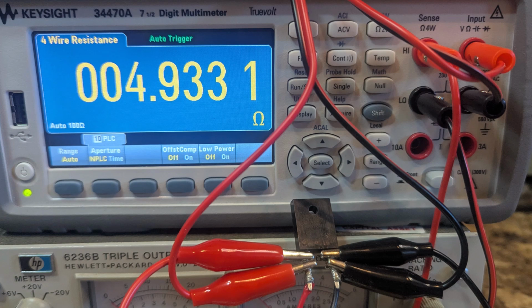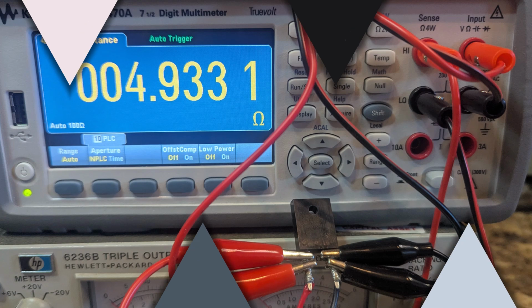So you can see just by adding that 32 gain using a precision op-amp, and it's very important that we mention that it's a precision op-amp, to get more of that ADC range, we reduce noise effects, we reduce any sort of low offset voltage error, as well as quantization error.